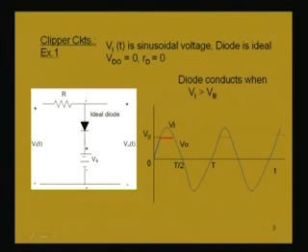So, the diode is non-conducting, there is no current flow, and this voltage V naught(t) will be exactly Vi(t). So, from this point until Vi is greater than Vb, up to this point, input and output voltage are the same. Again it will be conducting when Vi is greater than Vb. So, the output voltage V naught will be equal to this Vb voltage, and this will continue like that.